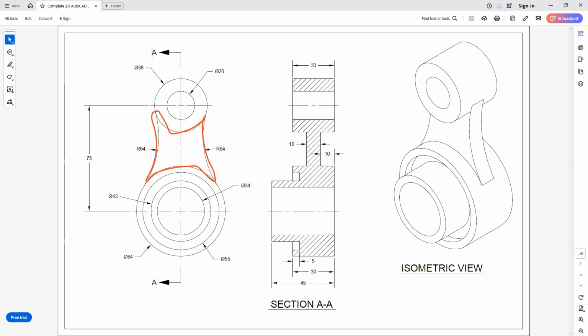The second parts that I'm going to need, and I have to decide how I'm going to approach this, is that I have 2 cylinders here, right? So if you know that we create things in AutoCAD or even in Inventor for that, and we're creating these 3D models, this can be done simply with just 2 cylinders and then me subtracting this middle cylinder from the inside of it, right? So I can go ahead and do this and get rid of this middle one, and then that'll create this top one. And then here on the bottom, I can approach this in 2 different ways.